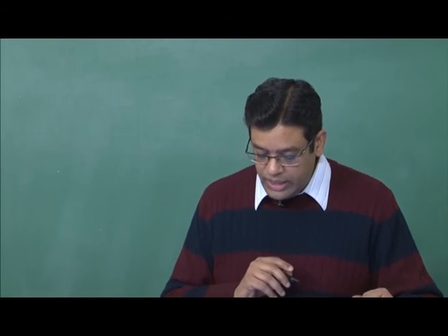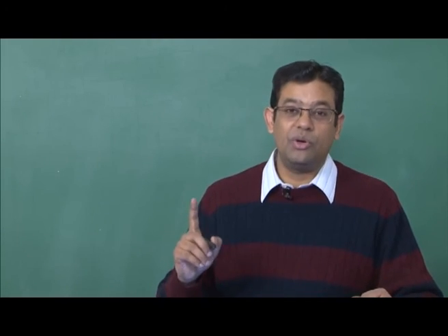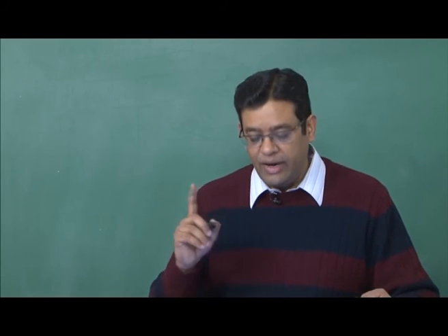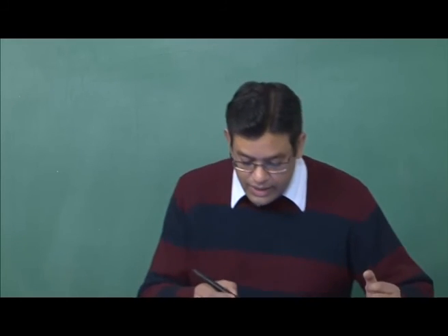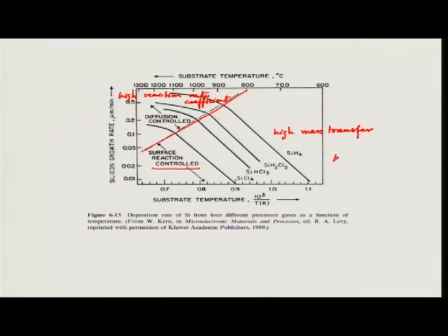However, if you are not able to control the temperature very effectively, if your temperature is varying at different places, then this reaction rate is dependent on temperature as e to the power minus Es over kT. So, the reaction rate is an Arrhenius type expression.